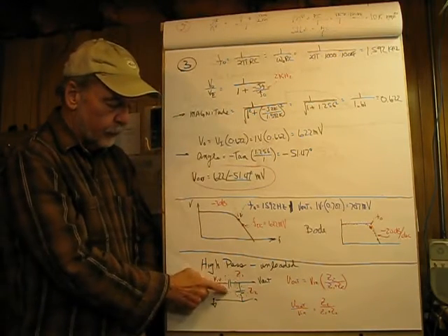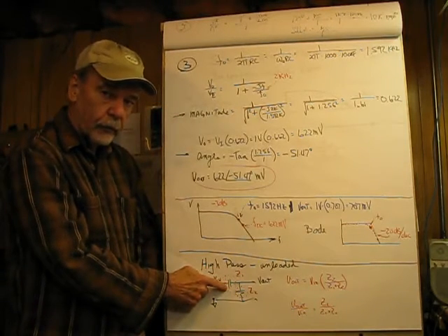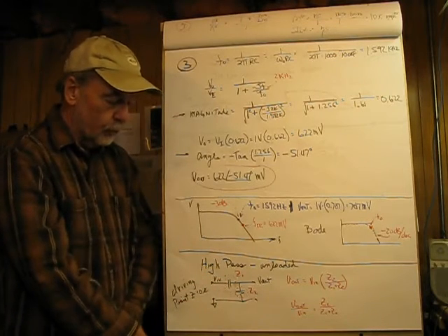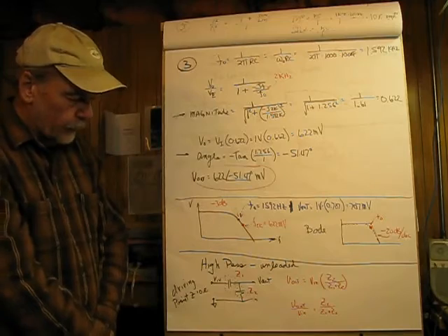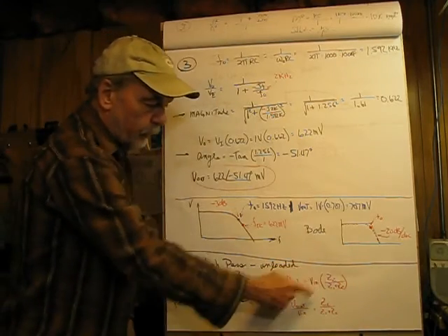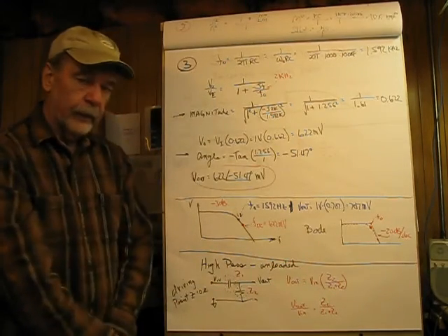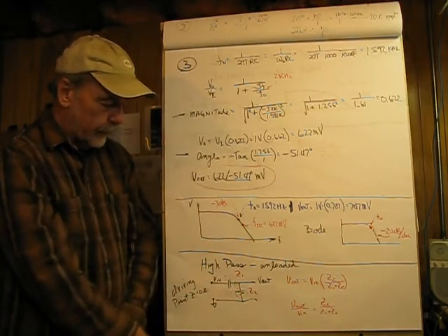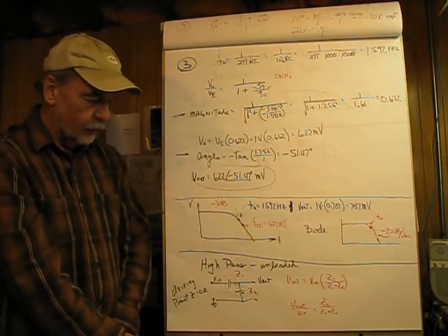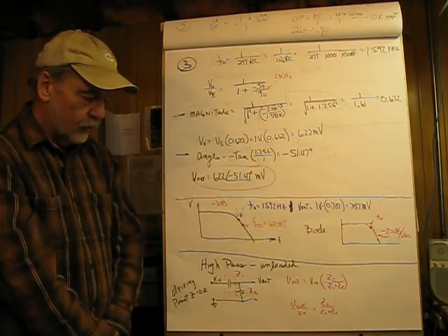And at low frequencies, this approaches an open circuit, meaning the output voltage would be 0 at 0 hertz. So setting this up would be the same as what we did before, and in the numerator we would have Z2, the resistor, and in the denominator we would have the sum total as before.